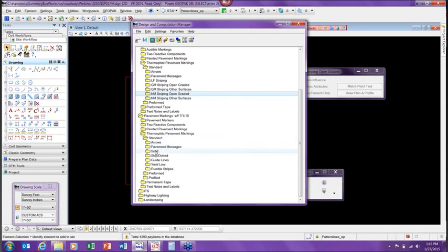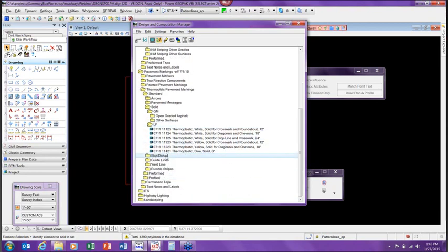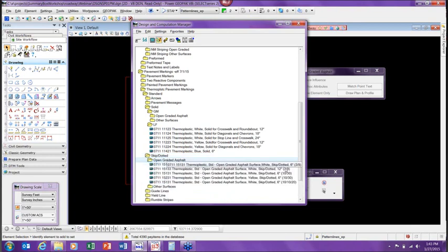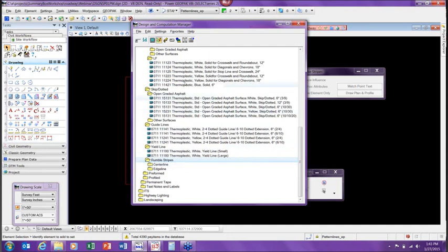So I've changed this up so that now you have a category for solid gross mile markings and linear foot markings. Then I have the skip dotted, which is my 3/9 and 10/30 skips. And then I have the guidelines, which is your 2/4 and 6/10 markings. And then the yield lines, I've just pulled out, so it's in line with the type of marking.